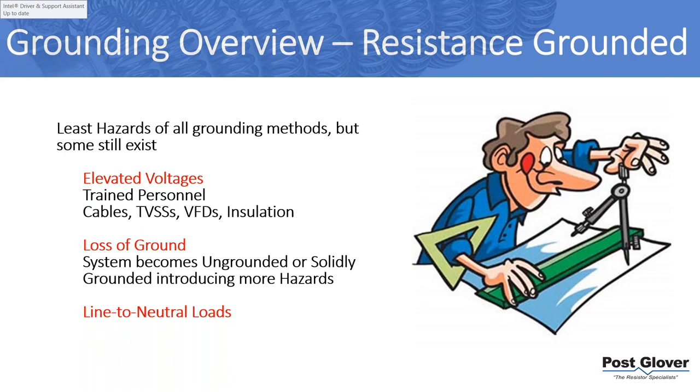Now I will say really quickly, I've never seen a resistor open up outside of shipping damage. If somebody drop kicks it off a truck, that's possible. However, in installation, a loose wire, a wrong wire, a missed cable, etc., you're not going to worry about.